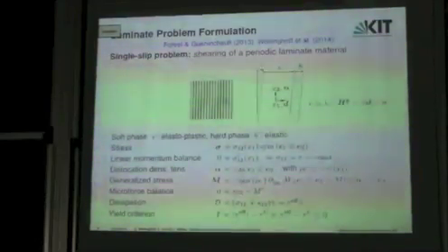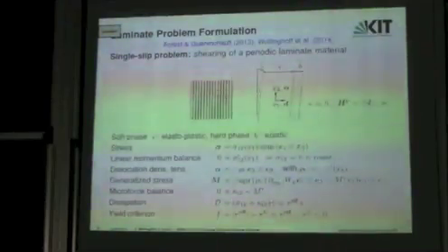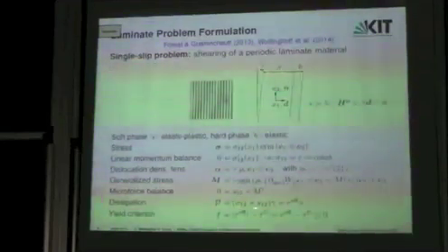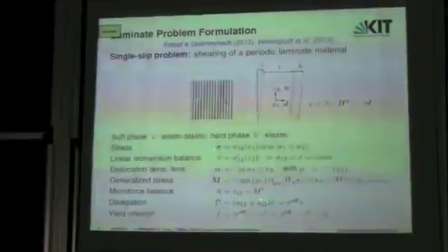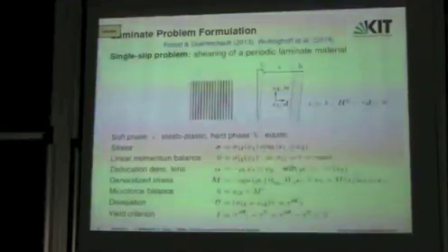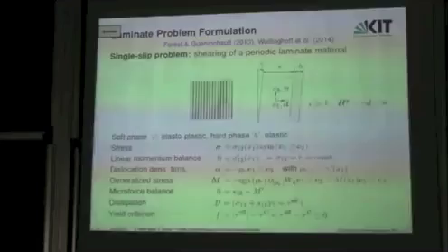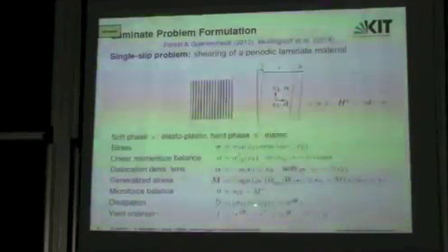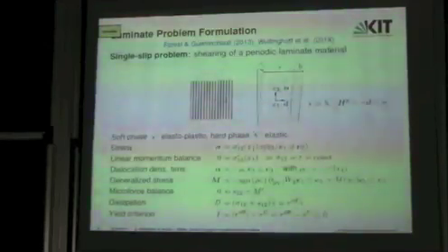turns out to reduce to a simple scalar differential equation, and from evaluating the dissipation we find that the plastic driving force here is simply the sum of the 1-2 components of the Cauchy stress plus the generalized stress M, which is conjugate to H^p.